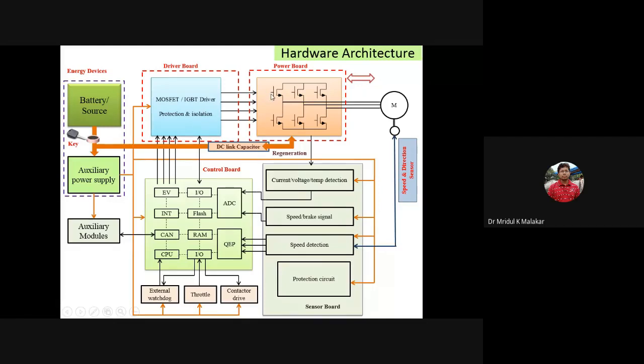The IGBT and MOSFET require a gate input. Suppose it is a 15 volt or 12 volt pulse, and maybe a maximum of 600 milliamps or 1 ampere is required. So this processor can't give that. It is a completely low power device. If the frequency is high, the device power will be reduced.